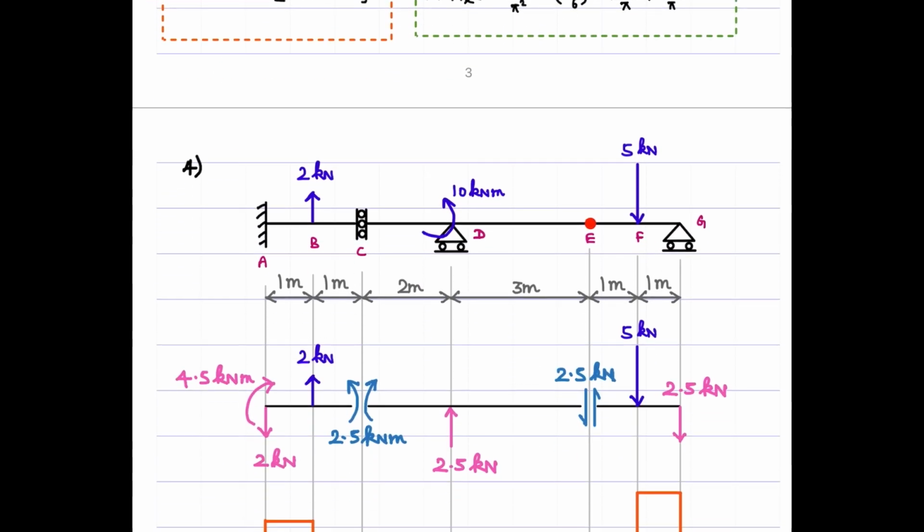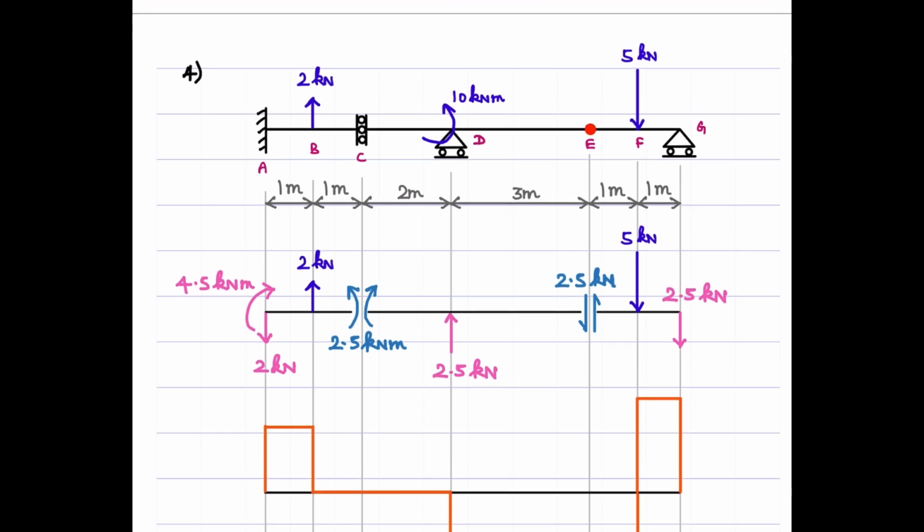Okay, we have finally a different beam, which is statically determinate. You have four unknowns, two here, one here, one here, two plus one plus one, which is four. Two static equations of equilibrium, and then two equations of condition due to the presence of internal releases here. You have a shear release here, and then you have a moment release here.